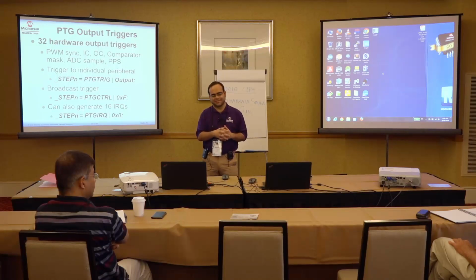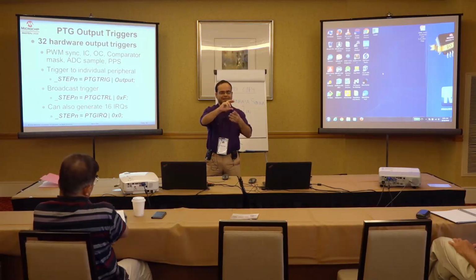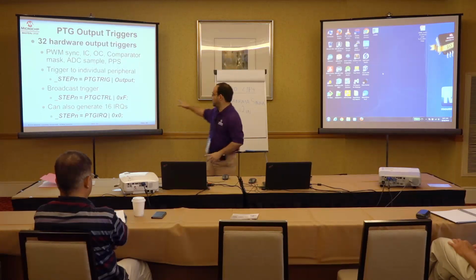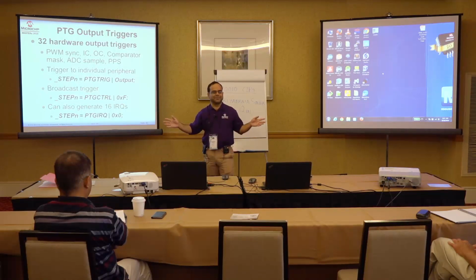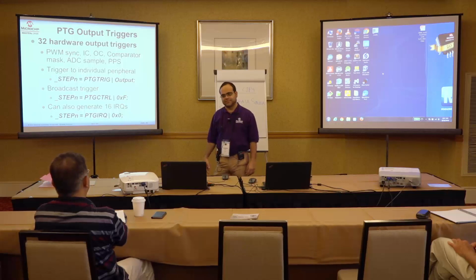It is an important, interesting point, because they are all handled sequentially. So, you wait for whatever is the most critical input trigger, and then the next one, and so on. But it's not so for output triggers, where there is such a thing as broadcast trigger. So, you can generate triggers to multiple peripherals at the same time. But for inputs there is no logical OR or anything like that. It's a bit field where you have to select a certain input.